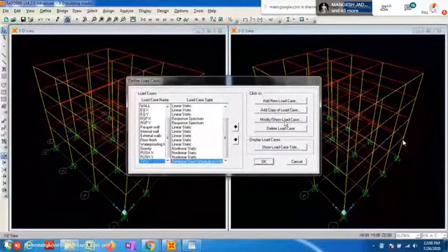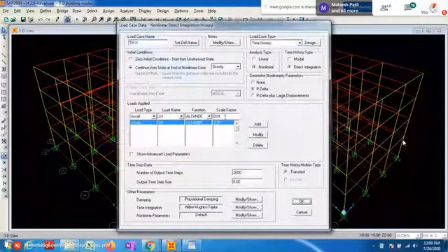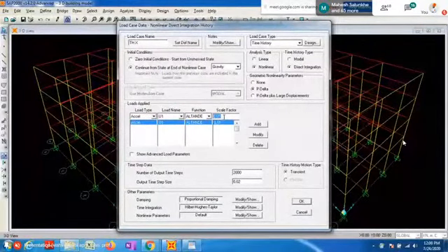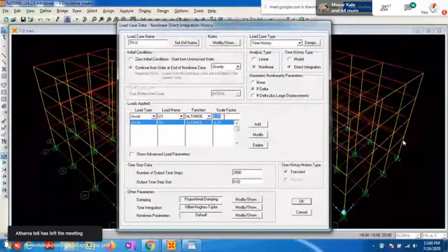This scale factor is to convert from centimeter to meter. Now here, suppose you want to perform the first analysis for 10% amplitude. So once again multiply this value by 0.1. 10% means 0.1. Run the analysis, get the maximum drift value, that is for 0.1 g.